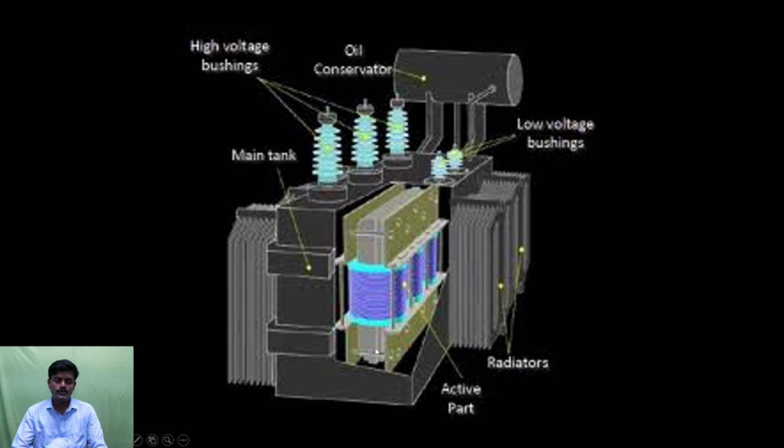In order to have the transformer oil in a container, here I am using the oil tank, the transformer oil tank. It's the outer cover. Here these are the cooling fins. When the winding is heated up, the oil also gets heated up. In order to transfer the oil heat to the atmosphere, here I am using the cooling fins. Oil is circulated through the fins and the heat is transferred from oil to the atmosphere. Then and there the heat is reduced.